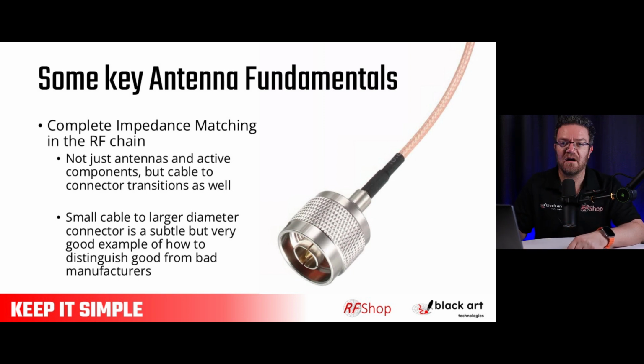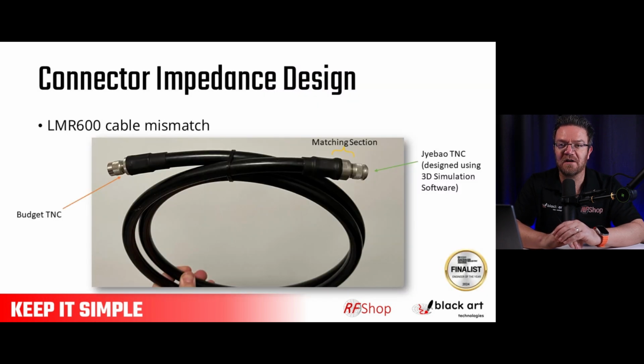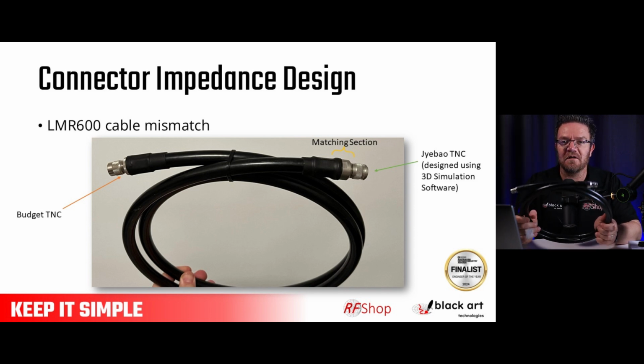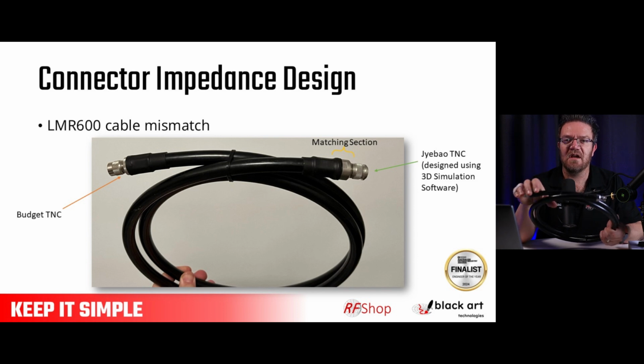Having said that, there's also an example of a big cable, LMR 600, that gets messed up quite badly. And this, again, becomes a real case problem that I would have had in my own life. There's the cable that I show you in the photo. What we saw was, we just thought we'll put a connector on LMR 600. This was a while ago, so we've learned our lesson. Don't worry about that. But we used just a connector from a supplier, basically TNC to LMR 600, and we had massive issues with performance of the cable.